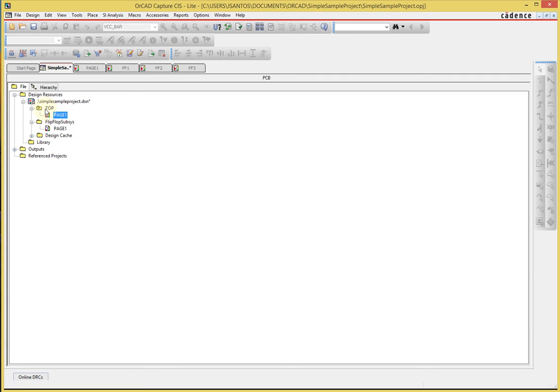page goes away. Now there's one last thing I want you to notice: the project manager schematic has a / next to it. This means that the schematic with the / is the root page, and this is necessary for hierarchical design. When you have a hierarchy, you have sort of like a pyramid. Well, what is the top design that connects all your blocks? You can designate a schematic as your top block by simply right-clicking and selecting Make Root. But because this one is already the root, it is showing ghosted. But if I wanted to make my flip-flop subsystem the root, which doesn't make any sense in my case, I would just select Make Root.